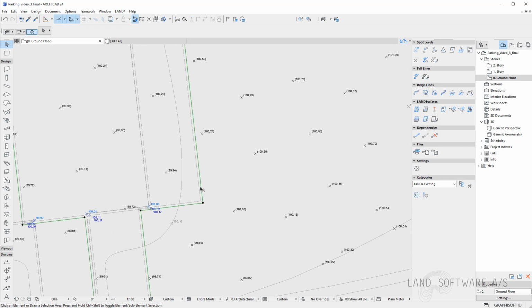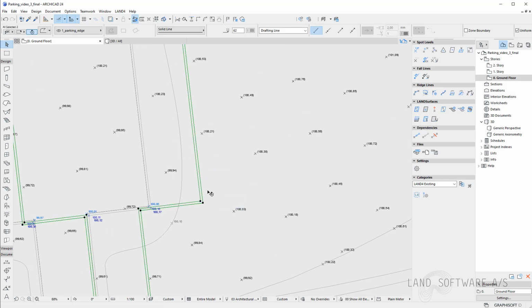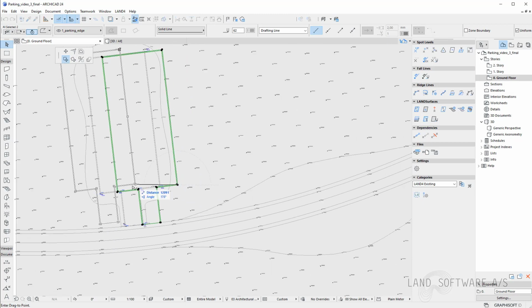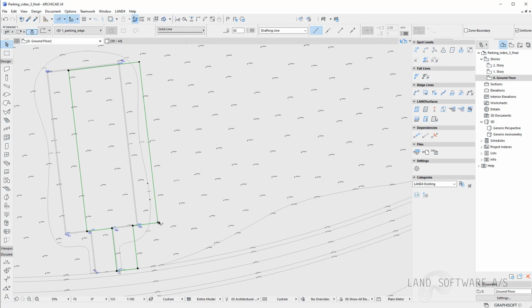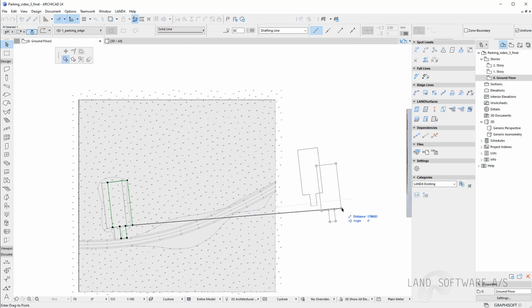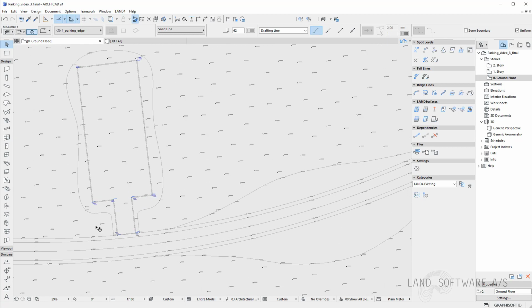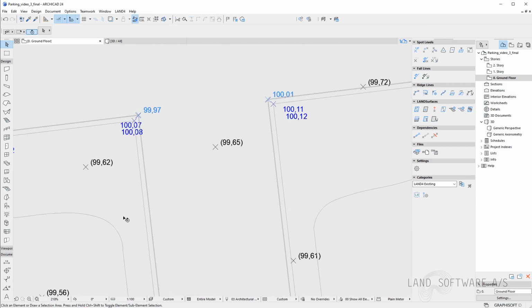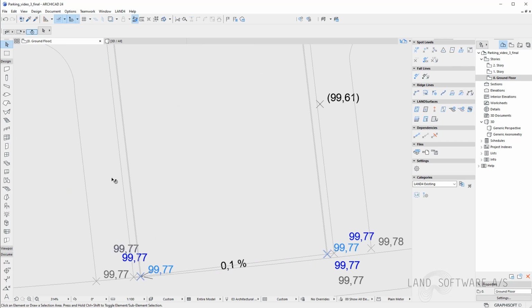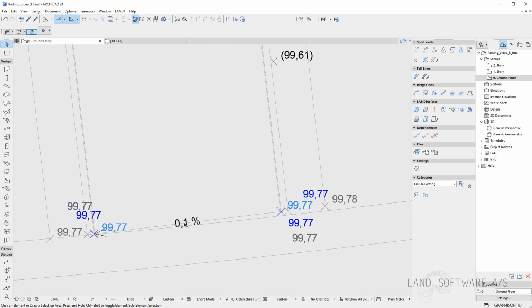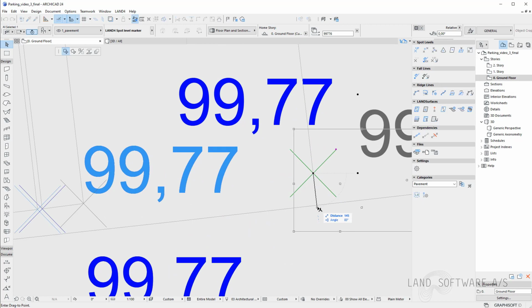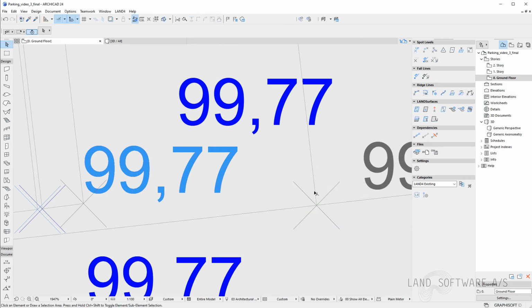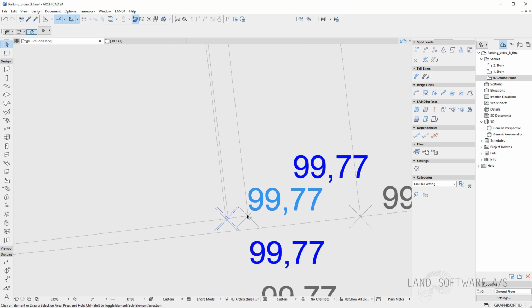What I see here is basically the polygons I use to create the ridge lines for the parking edge and the parking surface. So I'll place them outside there. And now I have my ridge lines. As you can see, of course, now it's not connected to the road. So I can simply just drag these spot levels together with the ridge lines and meet the road.